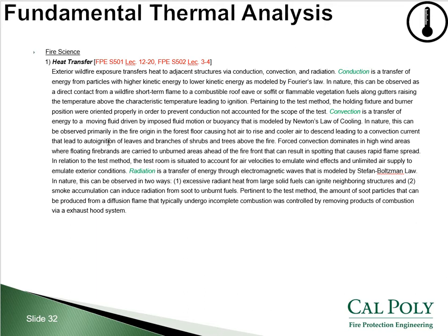So first, what's the relation of heat transfer and wildfires? Exterior wildfire exposure transfers heat to adjacent structures via conduction, convection, and radiation. Conduction is a transfer of energy from the particles with higher kinetic energy to lower kinetic energy as modeled by Fourier's law. In nature, this can be observed as a direct contact from a wildfire short-term flame to a combustible roof eave or soffit or flammable vegetation fuels along gutters, raising the temperature above the characteristic temperature leading to ignition. Pertaining to the test method, the holding fixture and burner position were oriented properly in order to prevent conduction not accounted for the scope of the test.